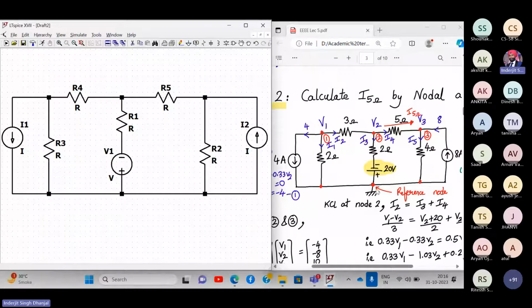Okay, now if you see carefully, we have a ground now. Even if our circuit doesn't have a ground, we have to see where the maximum number of nodes are connected. So the maximum number of nodes, we call it a reference node. All right. So at the reference node, we can connect a ground. So here, if you go left-hand side to the resistor, we see the ground. So click on the ground, place it anywhere below, and then join it with a wire. It's very mandatory that you connect the ground to every circuit. Without that, it will not simulate.